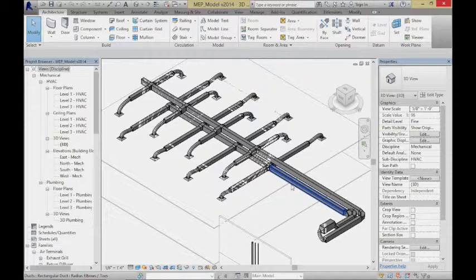We have something called an air handler, which is in the core space of the building. Air handlers really just have fans, they pull air through and blow air back out. And along the way inside that air handler, there are some chilling elements or some heating elements just to control the temperature, to condition the space, whether we need heating or cooling right now. But from that, we have some supply ducts and return ducts.